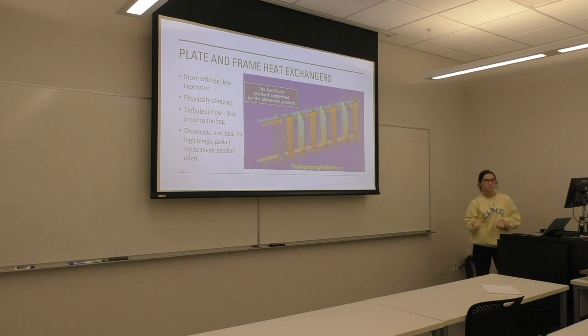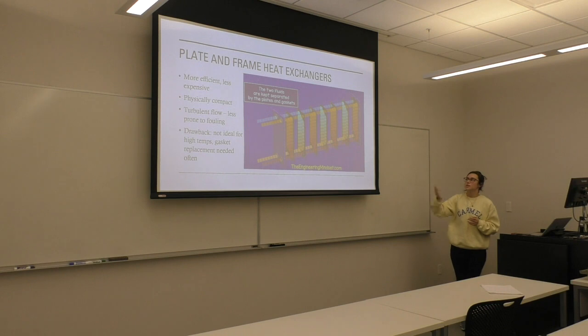But the reason why these probably aren't as common is because they aren't really ideal for high temperature cases, which a lot of heat exchangers are used for. The reason they aren't ideal is because of those gaskets, like I mentioned. As soon as you increase the temperature above a certain point, it dramatically increases how often you have to replace them.